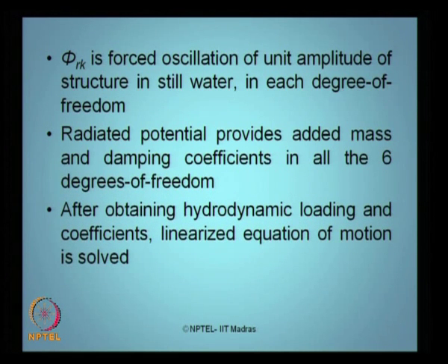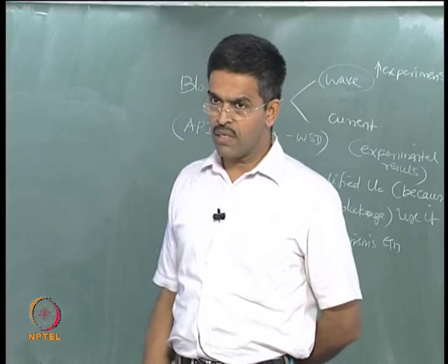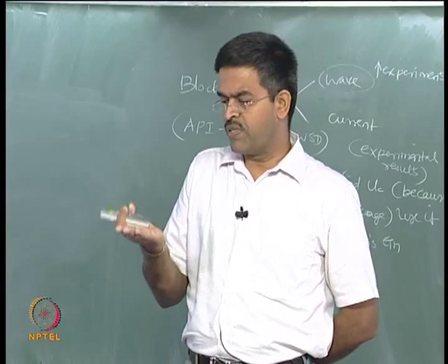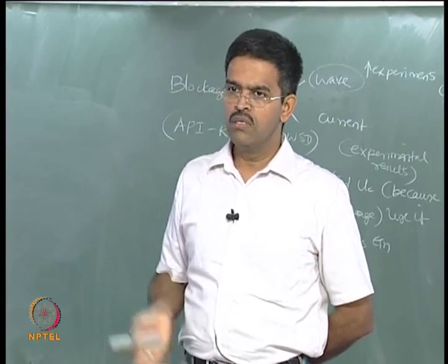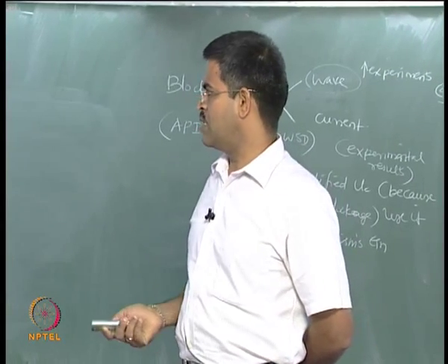After obtaining the hydrodynamic loading applied on my member, the linearized equation of motion is solved using different techniques, either in the time domain or in the frequency domain. That is how I do my dynamic analysis, incorporating FSI in my structural problem, where the cylinder is fixed, or large in diameter, or floating, where the surface of the cylinder is closer to the free surface or mean sea level.